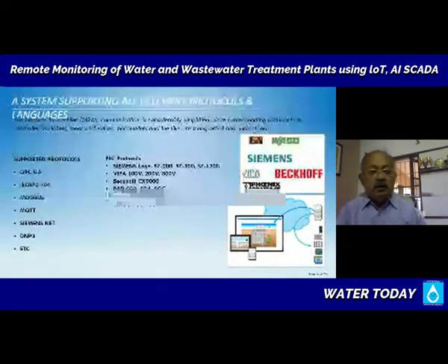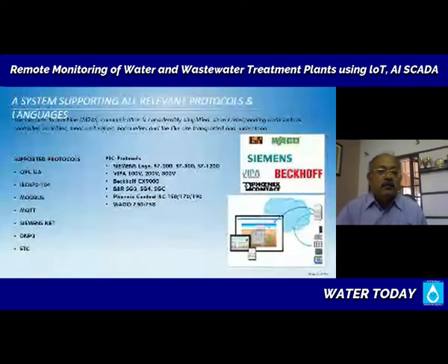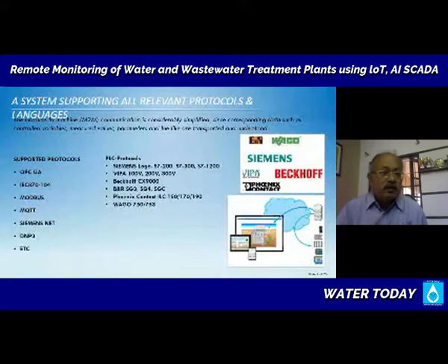If you are taking open solutions like MQTT, a modern telemetry transfer protocol, it is very light in terms of data transfer efficiency, and the accuracy checks are all very good, so you get good reliable data almost in a continuous mode in modern 4G and 3G systems. So you have to select solutions, including the sensors, the communication technology, and then the data management solutions, that are applicable for your application, is the point that I'm trying to make here.